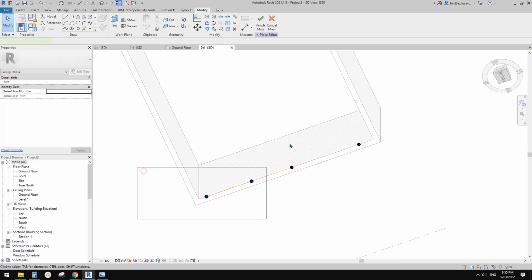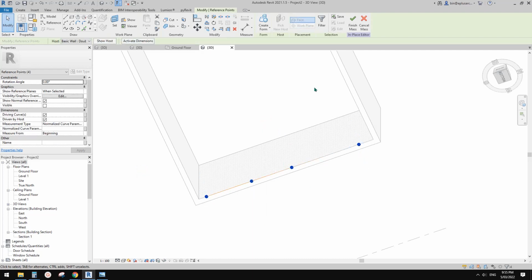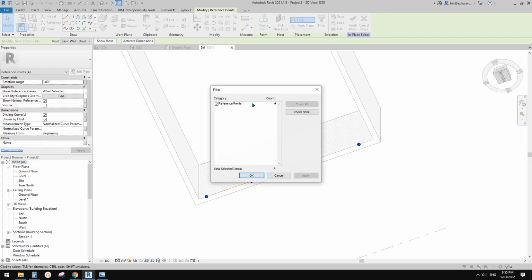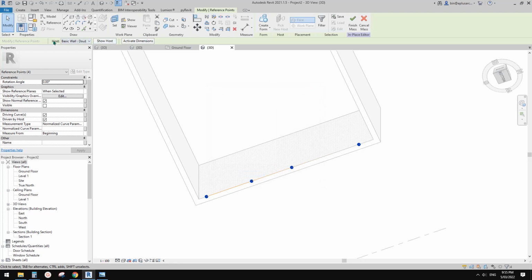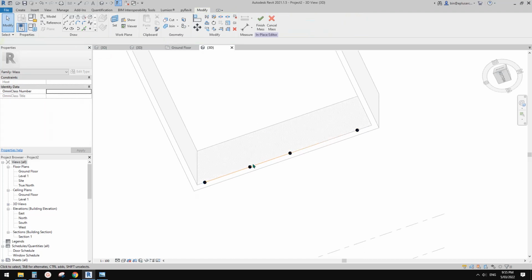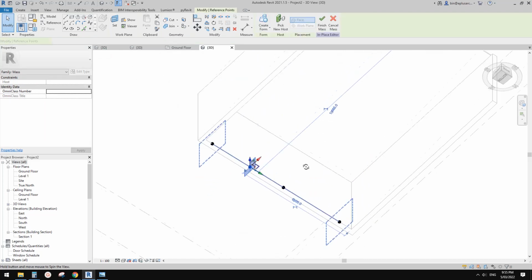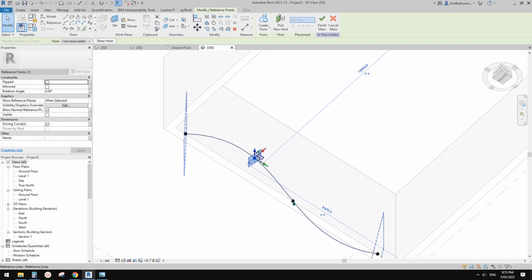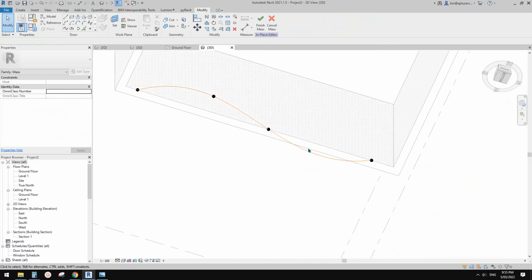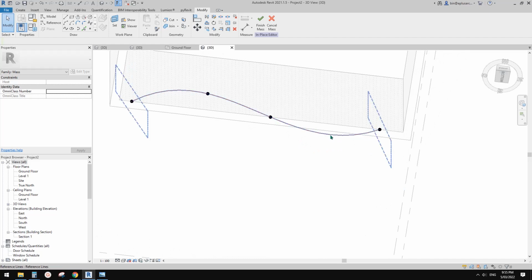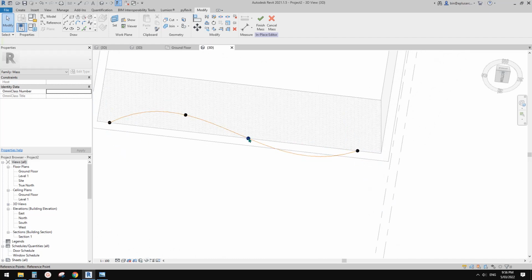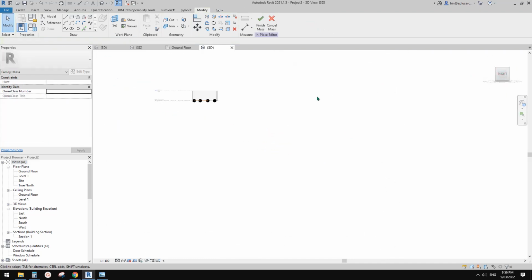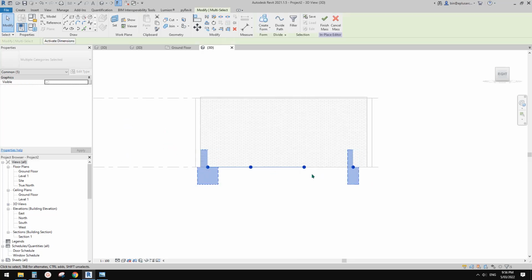So what you can do is select all these points, 1, 2, 3, 4 points, and go to here. See host, just change this to not associated. Now if you select the point, you can move it very easily. Okay. Actually, maybe 4 points should be enough. So I'm going to copy some. Go to elevation, in 3D, and then we can select this reference line.